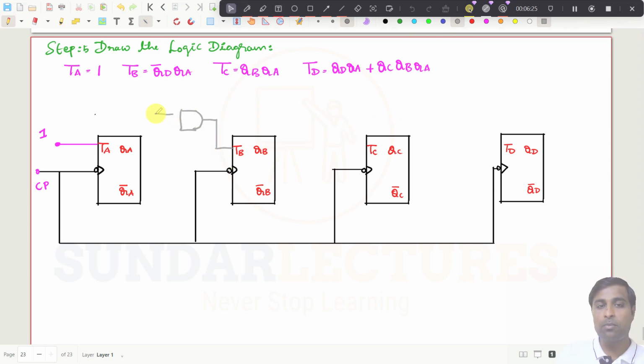And what is the input of this AND gate? That should be QA, that is one input. The other input should be from QD bar. You can get it from here. I am not drawing everything because it will be clumsy. You need to connect these kinds of things, so you can do it by yourself.